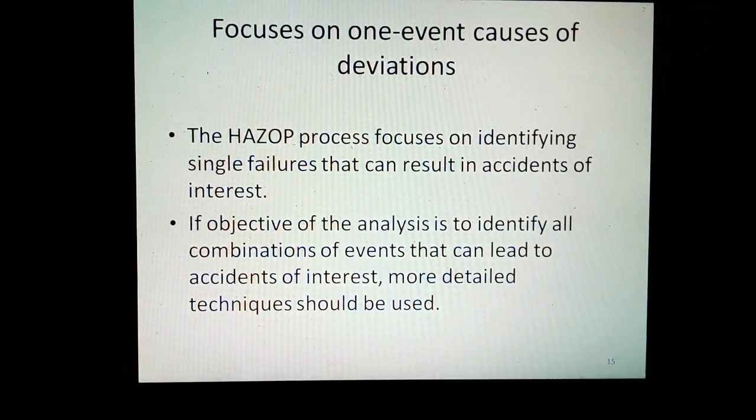Focuses on one event causes of deviations. The HAZOP process focuses on identifying single failures that can result in accidents of interest. If the objective of the analysis is to identify all combinations of events that can lead to accidents of interest, more detailed techniques should be used.